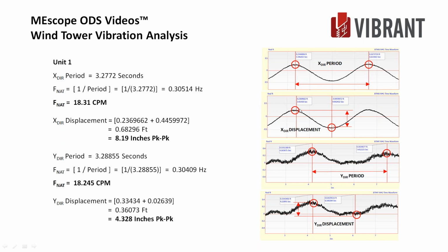This just brings it out and gives you the actual values. In the Y direction, you have another periodic event. Remember, there's 2 natural frequencies for any cantilevered system. There's a stiff direction and a softer direction. This was a little stiffer, or a little softer, I guess.